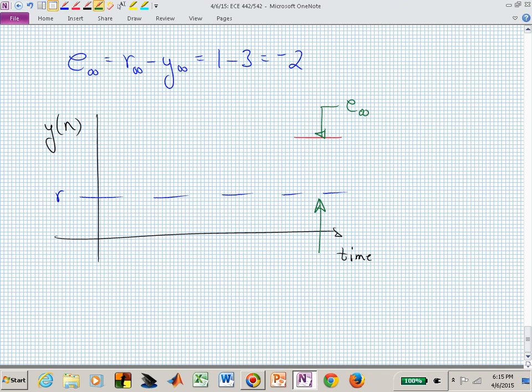How did you get there? What's the curve look like? What's the order of your system? First order. Does that tell you anything? When I say first order system, what are you thinking about as an electrical and computer engineer? You have one energy storage device, don't you? An energy storage device might be a capacitor, might be an inductor. You have an RC circuit.